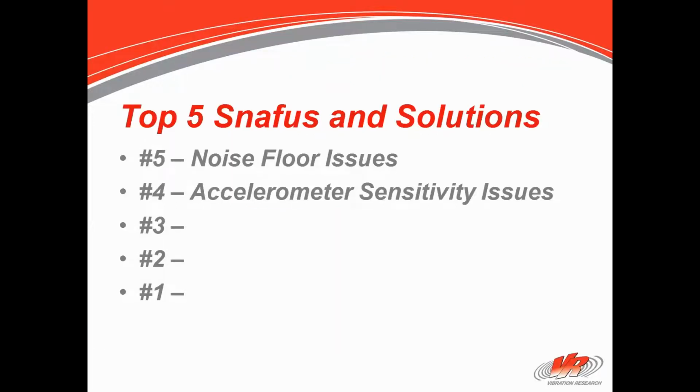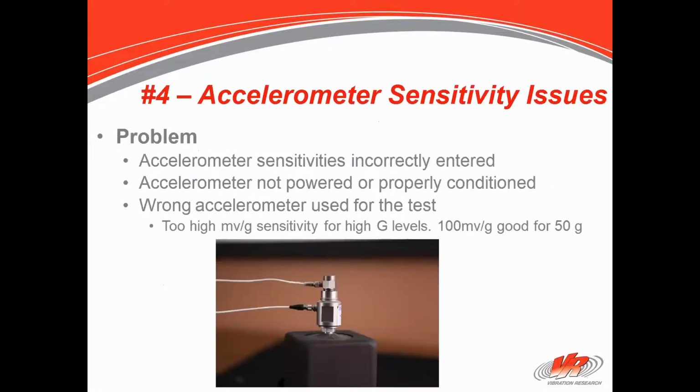Number 4, accelerometer sensitivity issues. That's a common question. What accelerometer should I use? The problem with the sensitivity issue may be that the accelerometer sensitivities are incorrectly entered.